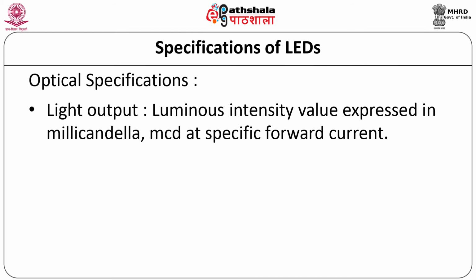Light output. The light intensity specification is not of crucial importance for most indicator applications, but with LEDs being used nowadays for lighting purposes, this parameter has become very important. The light output from an LED is quantified as luminous intensity value and is expressed in millicandela or mcd. The luminous intensity value for an LED must be quoted for a given current.